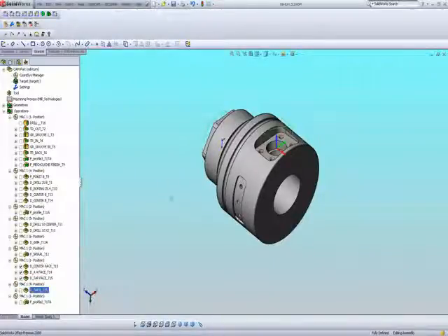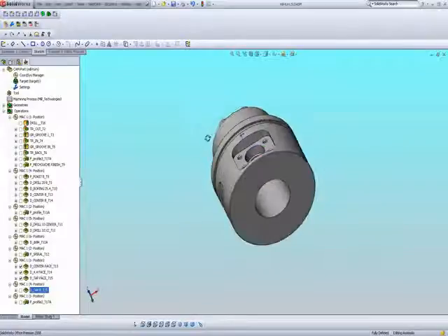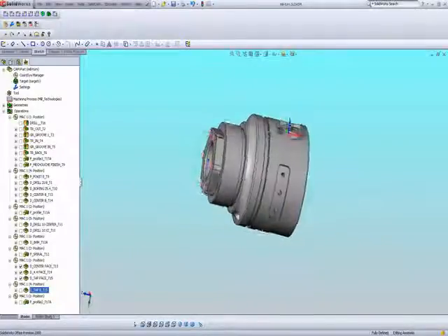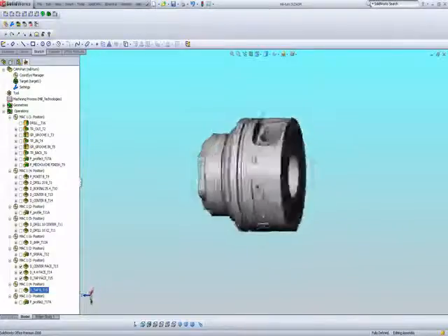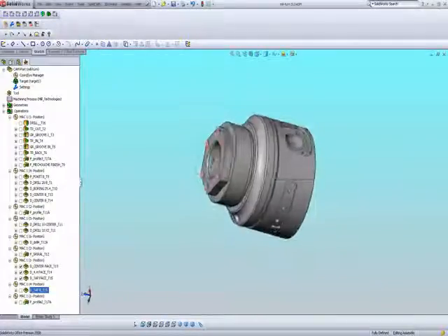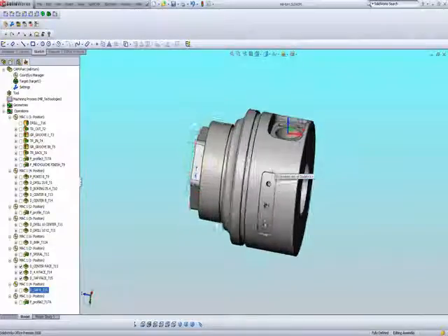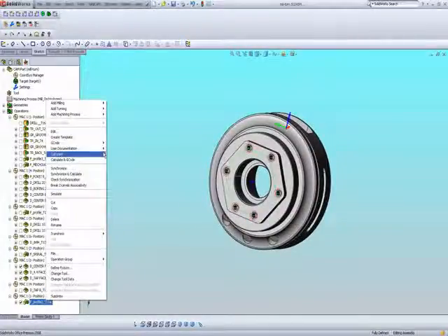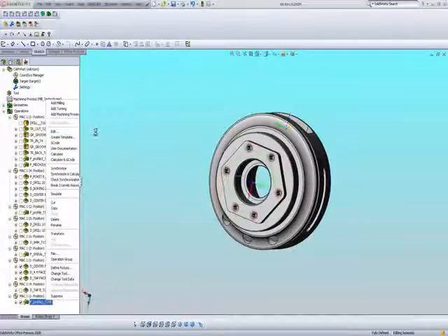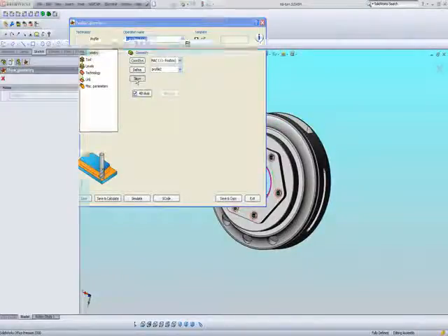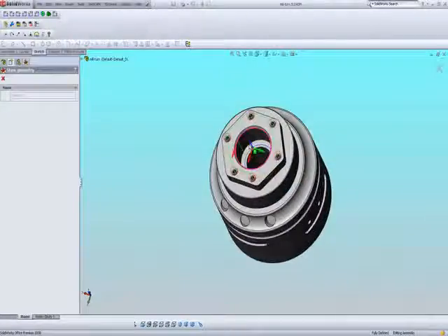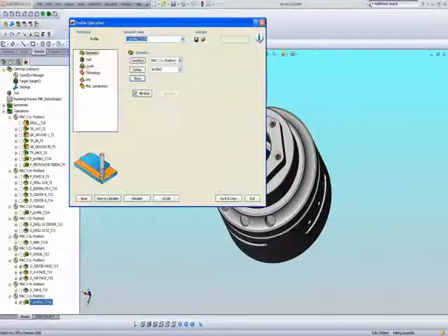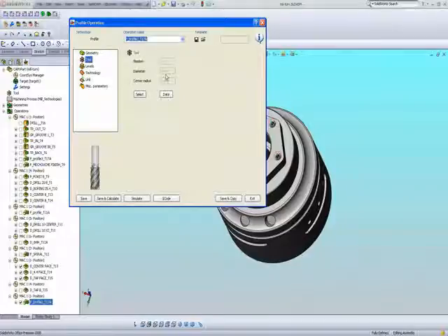What I'm basically showing here is I can go back and forth between every single home position, whichever order I want to do it in. I'm not locked into a specific position. I don't have to do it one particular way. And I have the same thing with my last operation. My last operation, actually, what I'll be doing is showing that this area over here, I'm going to just do a simple milling operation over here also. Notice I didn't have to do it by turning. I can also do it with a milling operation using a regular end mill,